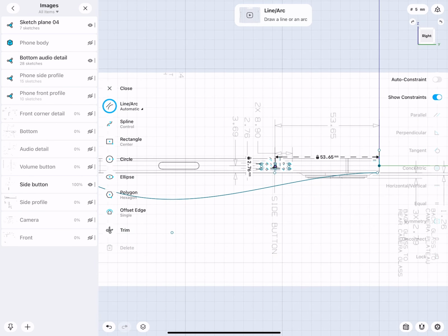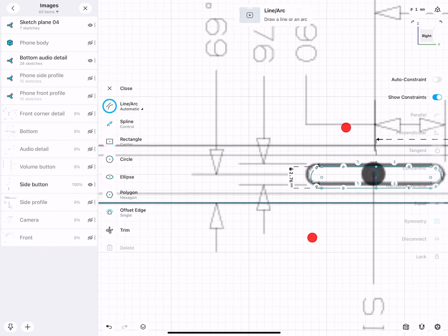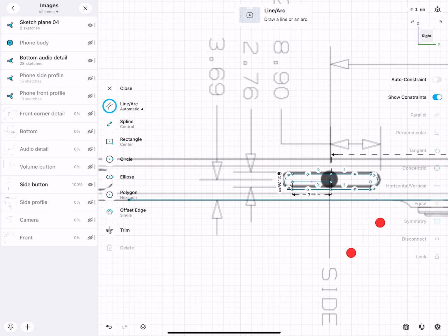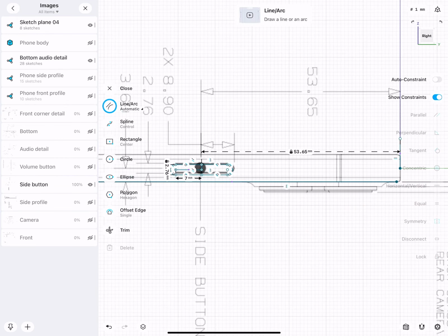So I will do the following. I will simply from this point draw myself a new line. Delete the curve. The starting point I lock, so I cannot rotate horizontal, and then I also lock this point, so I can't move anymore. And I have here my midline, and there it says from the midline to there 3.69. But this is actually also with the glass now, so keep that in mind.